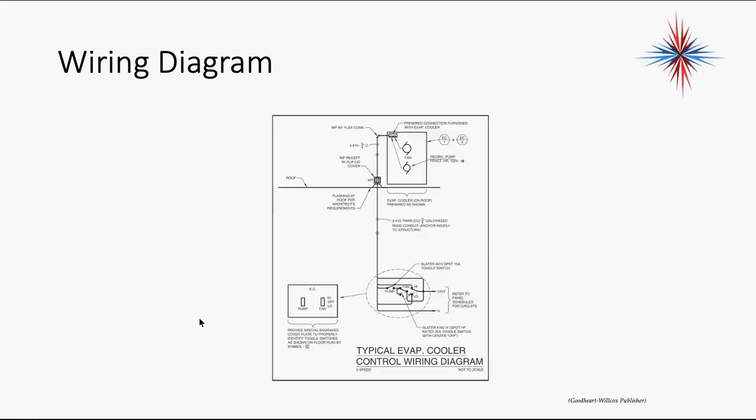So this is an example of a wiring diagram. We might have wiring coming to the right here, coming to the panel connections. 120 volts and neutral. This happens to be an exhaust fan. It's showing us that there's going to be a switch installed on the inside, and then the wire is going to run up to the roof, and it tells you the weight.